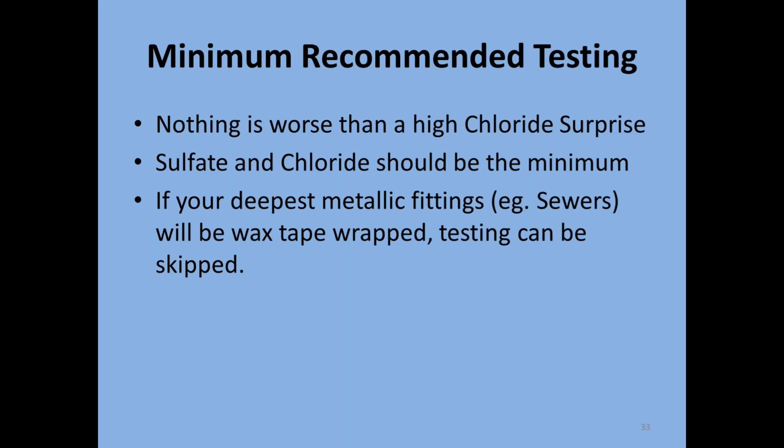Let's see, just something to cover. For sewers, which are typically very deep and usually have very low oxygen levels, if the metallic fittings are wax tape wrapped, then testing for chlorides and sulfates and this kind of chemistry at those levels can be skipped, because wax tape is a fantastic coating for separating soil from the metallic surfaces, and it will stop the corrosion very well.